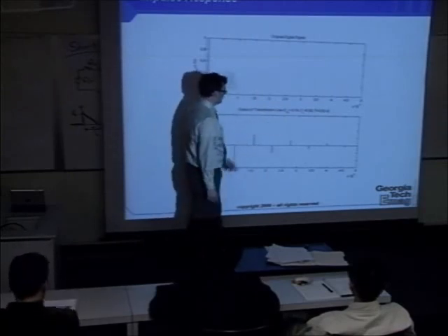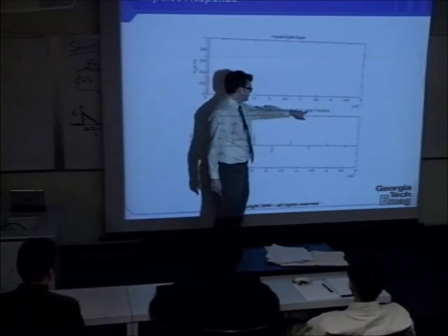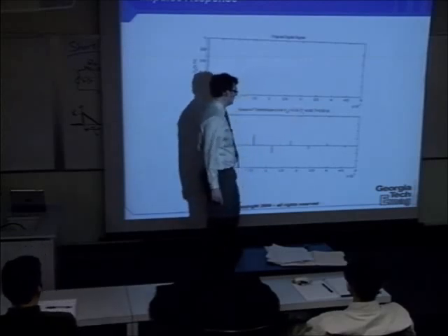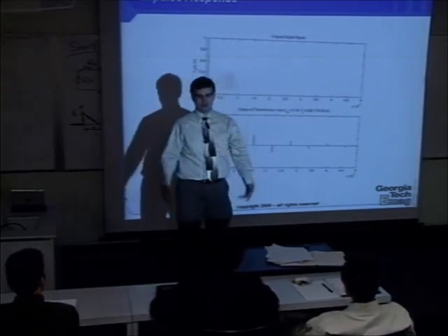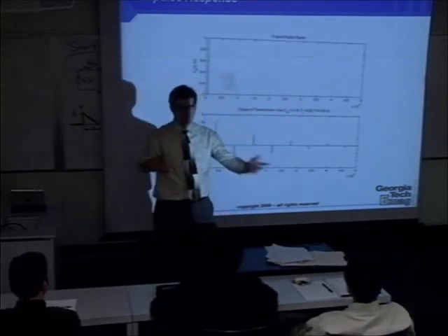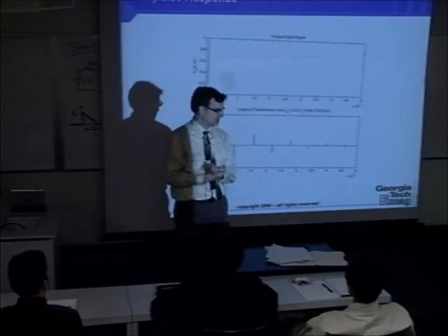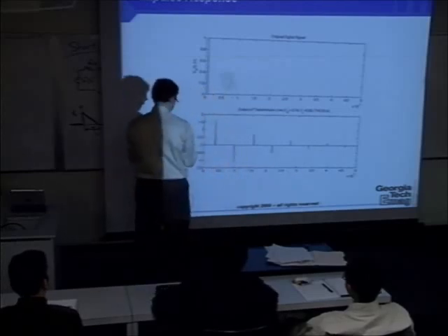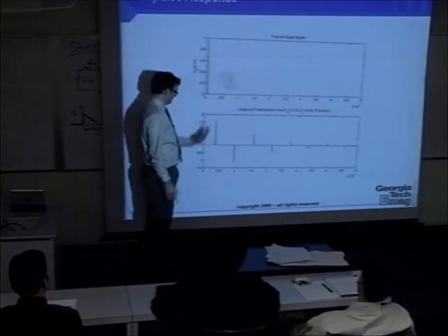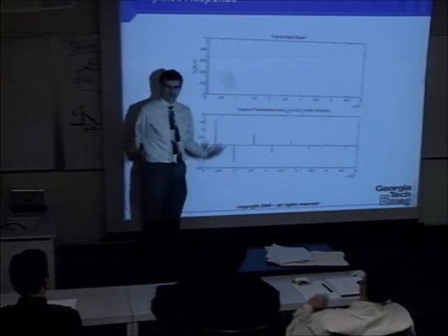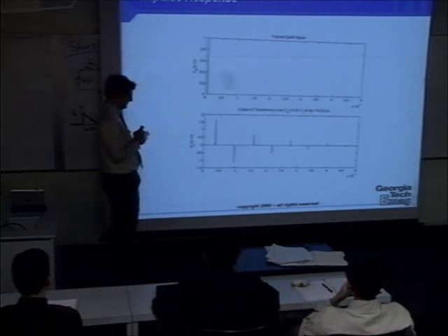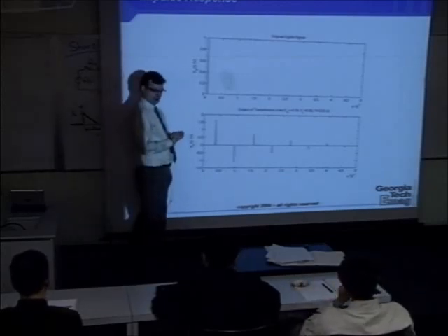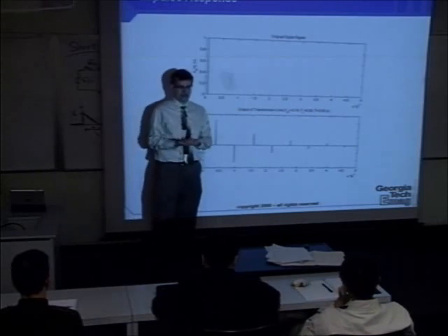In this case, our reflection coefficients are 0.9 at the load and minus 0.74 at the source. So we got a pretty badly mismatched line. This would be typical of a carelessly connected pair of logic circuits. So look at that. It looks a little different than the ringing we've been seeing in the DC circuit case. But tracing out an impulse response is actually a pretty useful exercise, right?